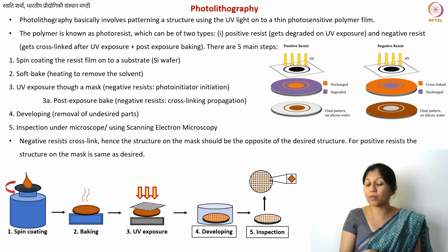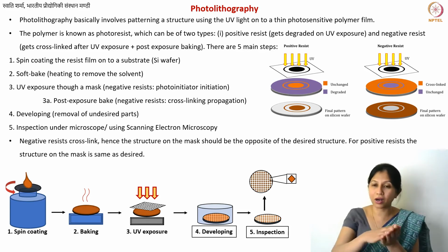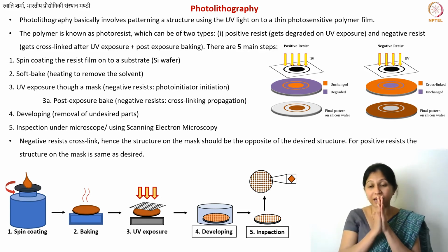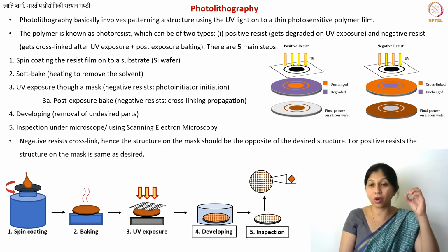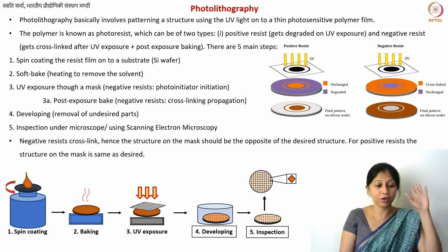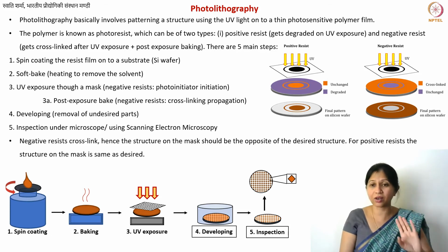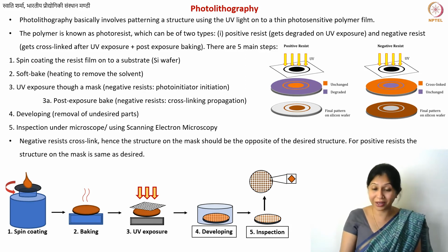But at the same time, you may get higher graphitization. Higher graphitization means higher order. Now this glass-like carbon is a non-graphitizing carbon. So it will never convert into polycrystalline graphite. Keep that in mind, because you always have these curved carbon structures, these fullerene-like structures, that are not going to give you 100% graphite. You're not going to get even polycrystalline graphite. That is why they are called non-graphitizing.